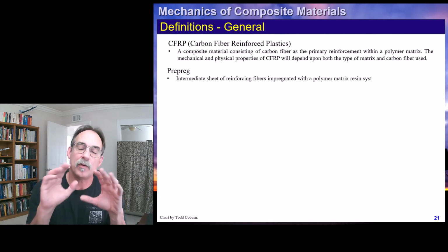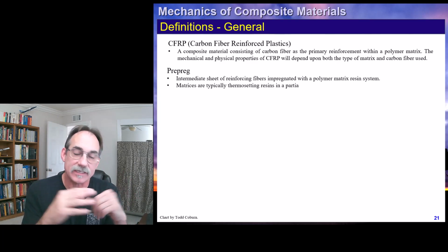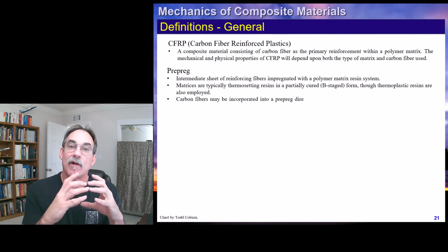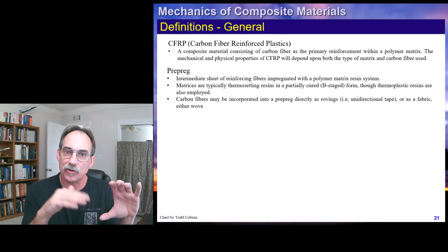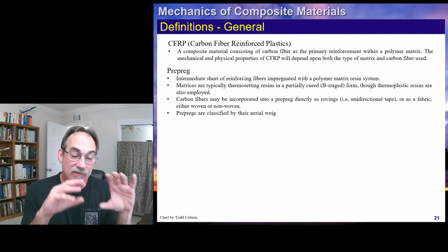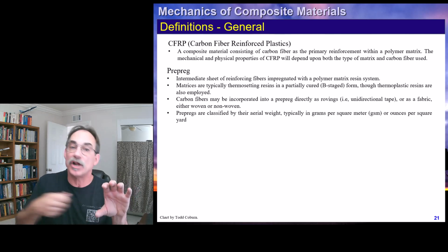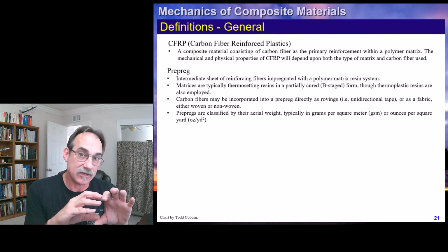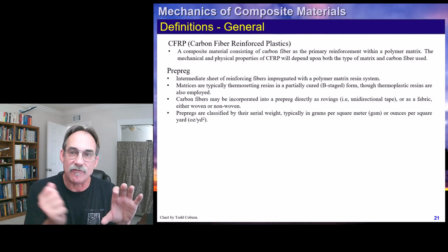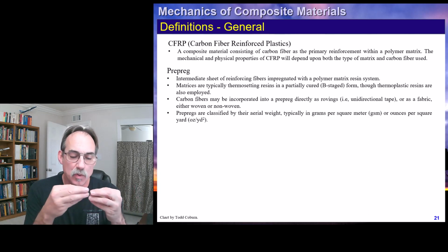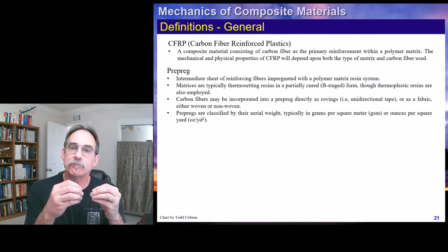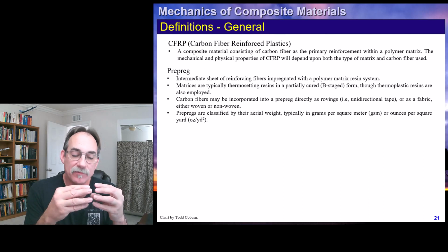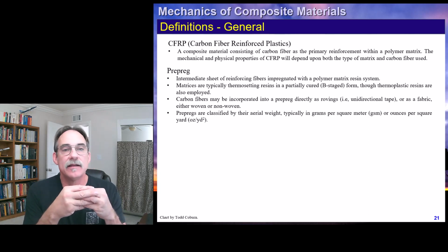Prepreg. Now this word prepreg, remember we've talked about fibers and matrices. One way to make a composite is to lay out your fibers. Let's say we are making a rocket tube, and so we wrap our fibers around a mandrel and lay them and then wrap them. But then we've got fibers, we don't have any matrix. So one way to do this is to brush that epoxy or whatever our matrix material is on the fibers until they get fully wetted and they absorb that. So it's between the little strands of each tow or yarn, and around them, so everything is wet with this.